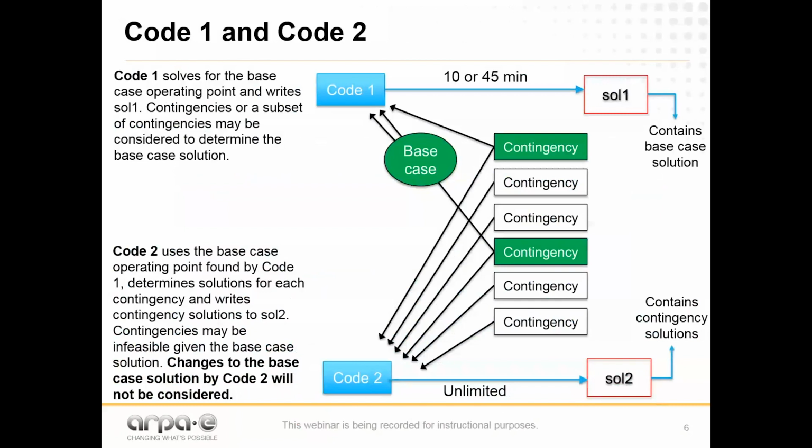The problem that we are providing to you is known as a two-stage stochastic program. There is the first stage, from a power systems perspective, that's our base case, and the second stage, which is the post-contingency case. The right way to solve this problem is to solve the entire problem altogether, considering all contingencies, to make sure that you get a common base case solution that's reliable against all single contingencies that we are defining for this security constrained optimal power flow. That's the best way of attacking it, is to solve it all together.